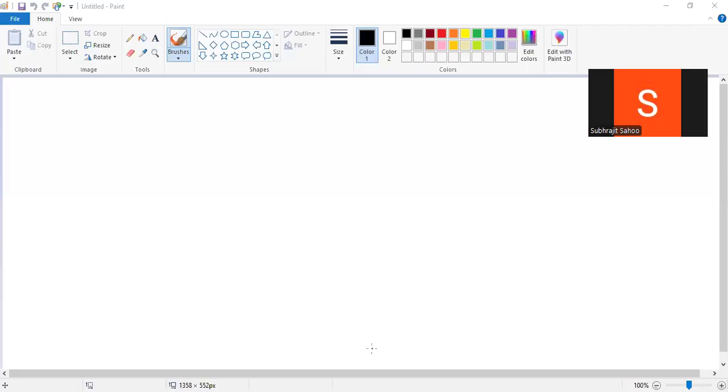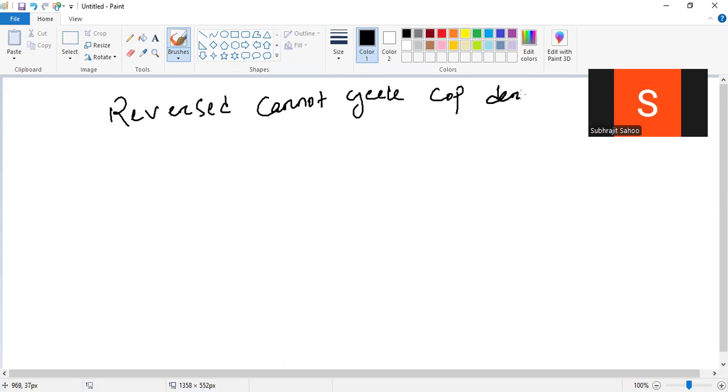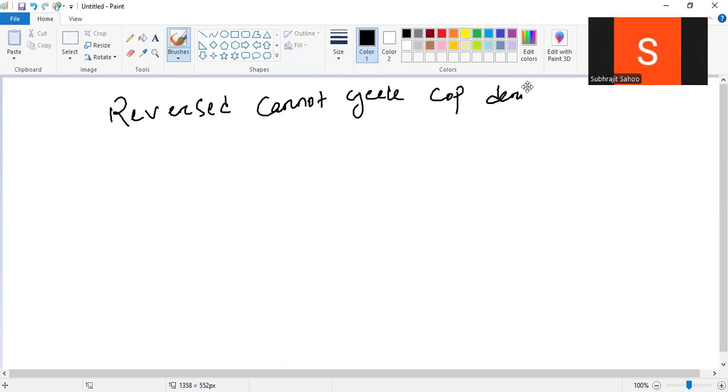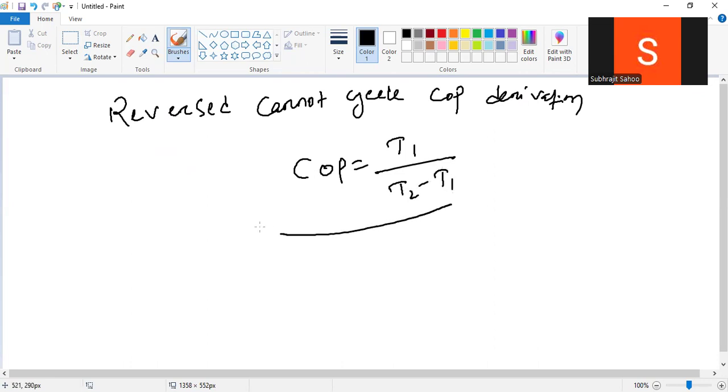Already two classes we have covered. This is the third class. In the last two videos we have completed up to which topic? Up to the reversed Carnot cycle COP derivation. Up to that, we have completed the derivation, right? So, what formula did I get? COP equal to T1 divided by T2 minus T1. Okay, I will tell it once again, don't worry.